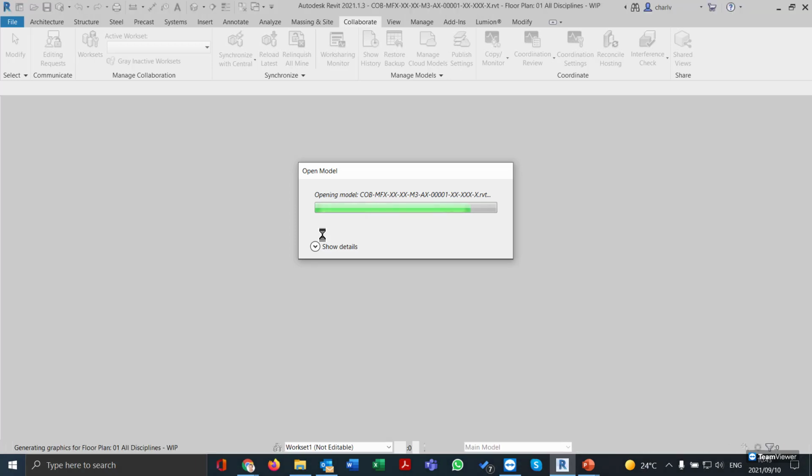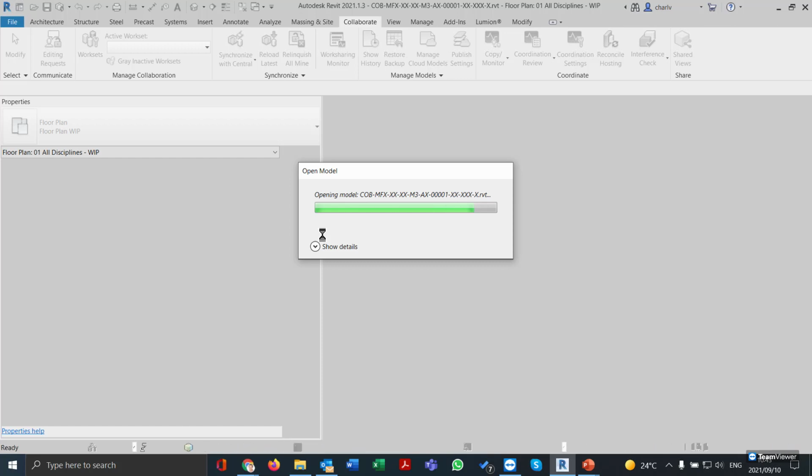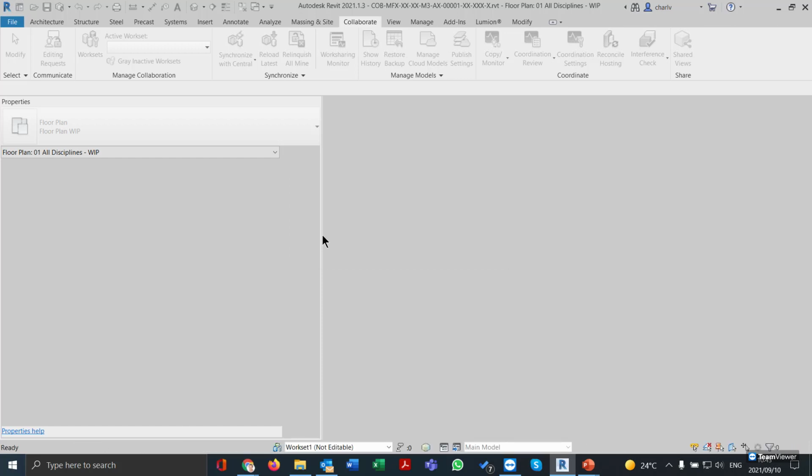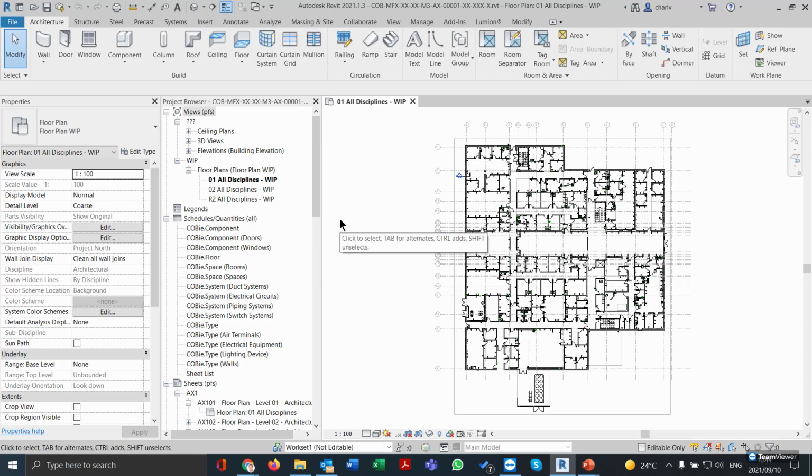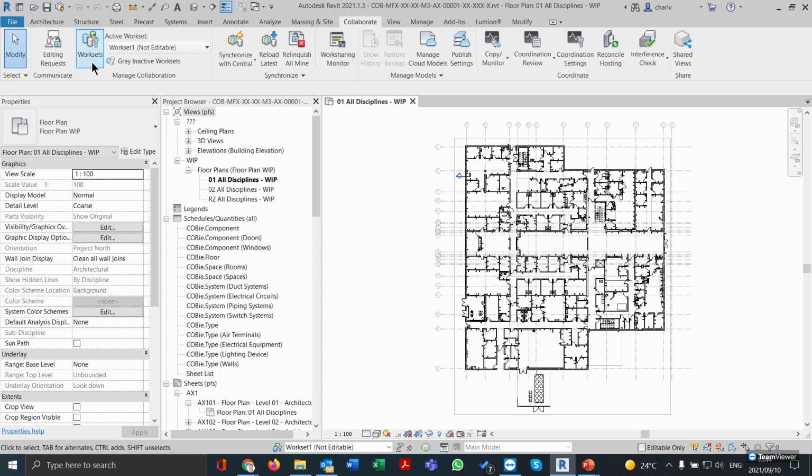My colleague would have internal walls, and the other guy will have maybe the roof. And we'll work in tandem in the same model, co-authoring everything. And then as he changes something, he uploads, I'll get his changes and so on. So the worksets environment works very similar to a local workset in a local area network or your kind of company, but you would perhaps just sit at home doing the same thing.